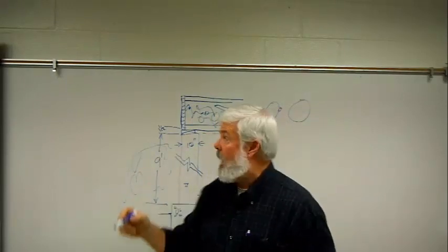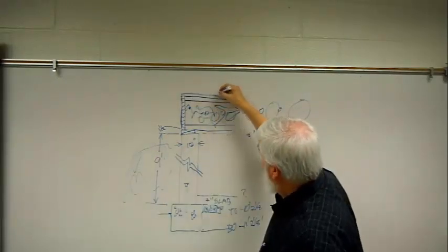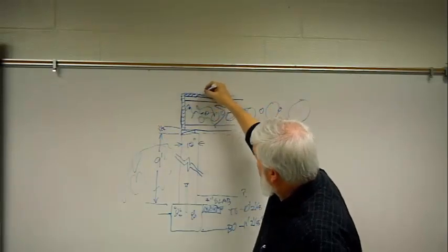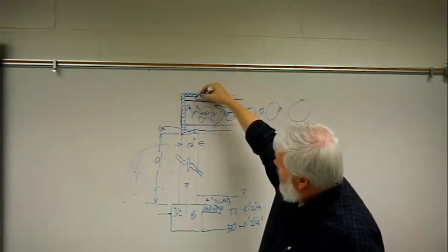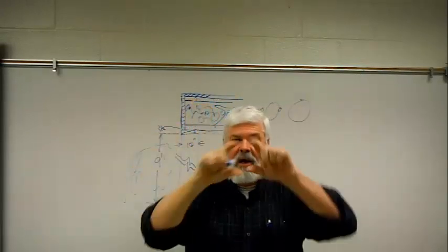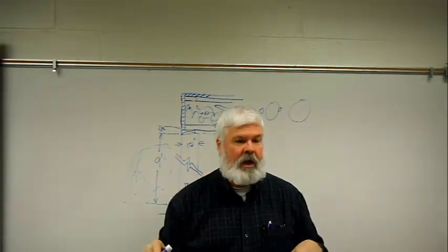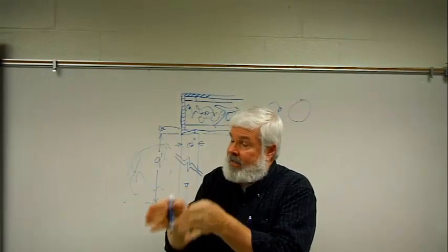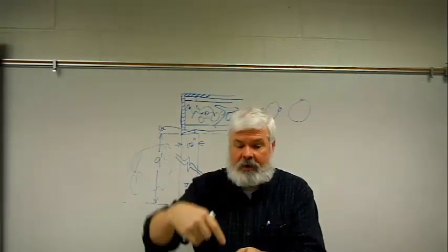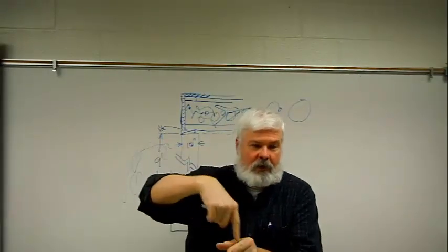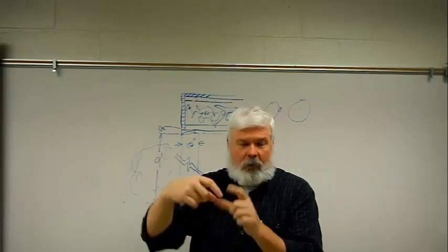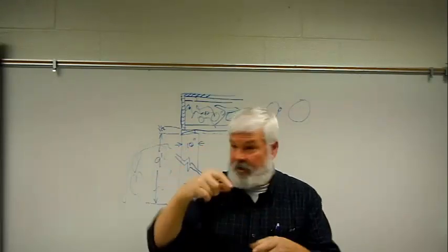The reason they called it a silent floor system is because this plywood that's nailed to the top gets nailed into this top strand, which is a laminated material. And so unlike a conventional 2x10 or 2x12 floor joist, the nail is not going in between the grains that run that way. And when the wood dries out, the nail can move up and down and squeak.